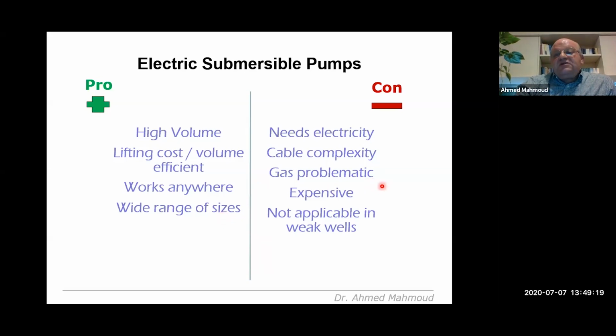Now, some cons. Mainly, you need electricity. So if you're in a place which is pretty remote and you cannot connect to electricity, maybe the ESP is not the best for you. Cable complexity used to be a problem in the industry previously, because you had to install the pump and pull the cable to it.